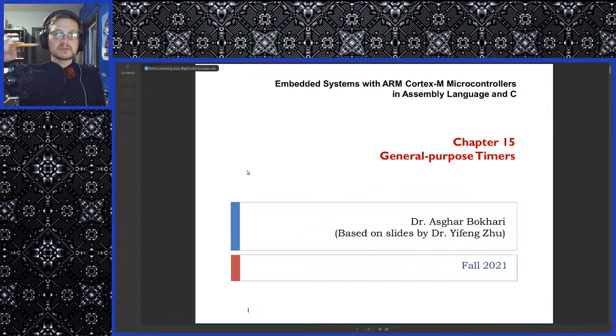So these are timers which are dedicated chips, dedicated ASICs that are external to your processor that are communicated with via the GPIO interactions that we have been studying previously. You know, if you want to wire up a separate one, or if you've got one included on the board, which your boards will have one included, then there's memory map. There's some memory which has been mapped to these timers, which you're free to use in the same way that you use them for GPIO.